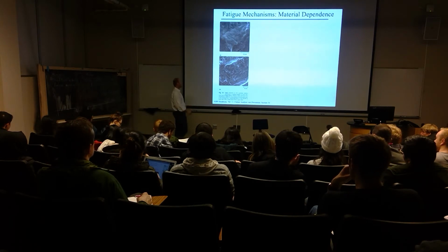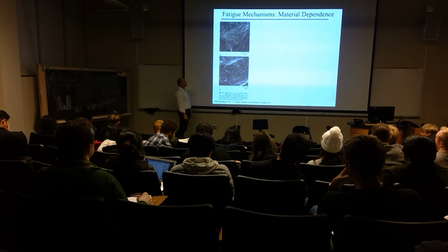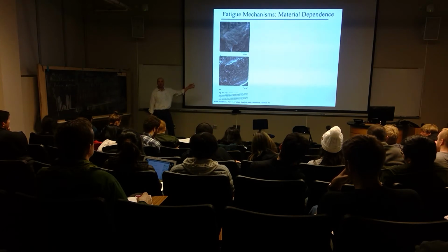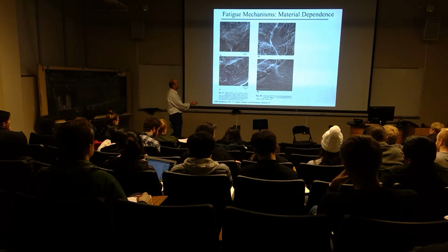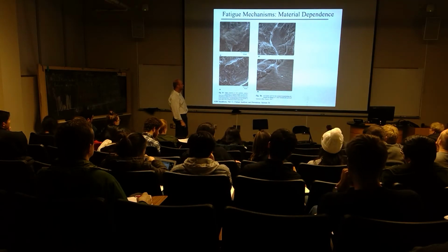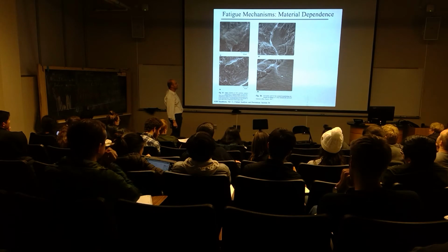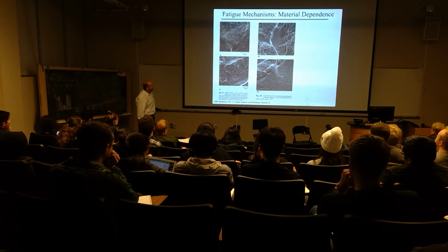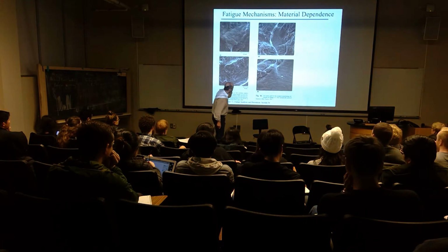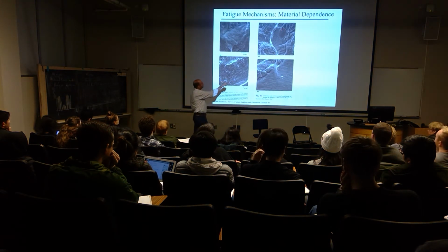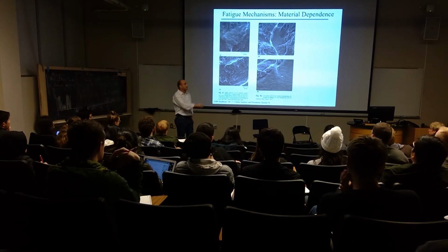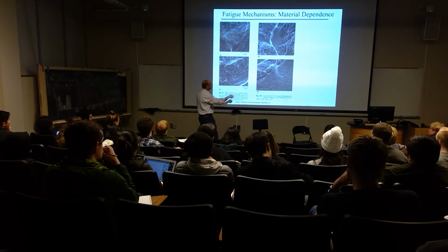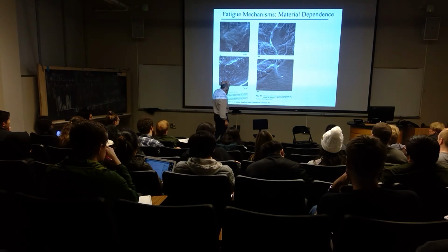So these are striations of that same material, but closer to the overload area. So we know that the magnitude of the stress intensity, the driving force, was greater and causing bigger striations, more pronounced for the same material. So here we see, for example, very coarse striations, and then fine striations that you see on a hot isostatically pressed titanium alloy. And in both of these, you can kind of tell what's going on in terms of the orientation. So here, for example, I see that there are striations that are increasing in amplitude. What direction is the crack growing? From top to bottom. I look at these striations that are present here, and I'm looking for features that help me understand. What do I see?